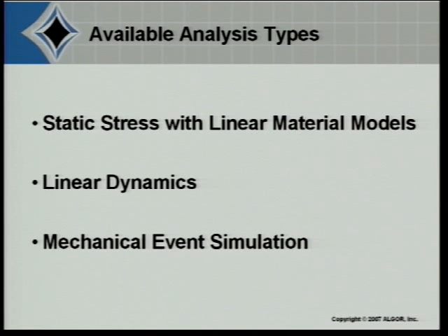And last but not least is our mechanical event simulation, MES analysis type, that also has the composite element as a subcategory of the shell elements. Actually, you would have to go to enhanced shell elements and composite, whereas for the linear analyses, they are their own element type and not a subcategory.